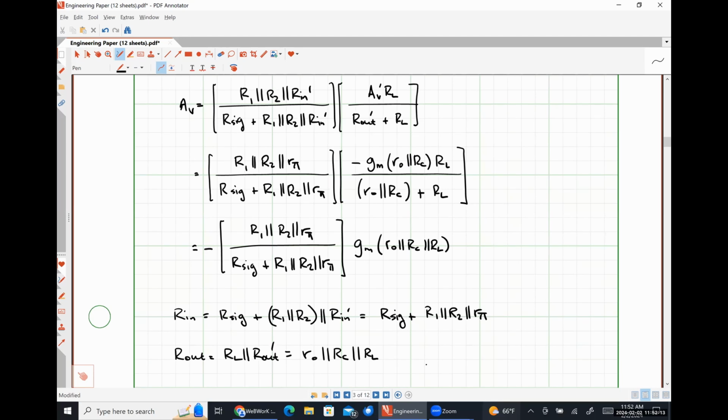We know what the trade-offs are with trying to increase the voltage gain so that we don't accidentally push it into clipping because we're too close to VCC, or push it into saturation, clipping our negative half cycles. We've got a pretty firm grasp of this guy. That's a concept that's typically called headroom. So we have enough information here to calculate our voltage gain, right?